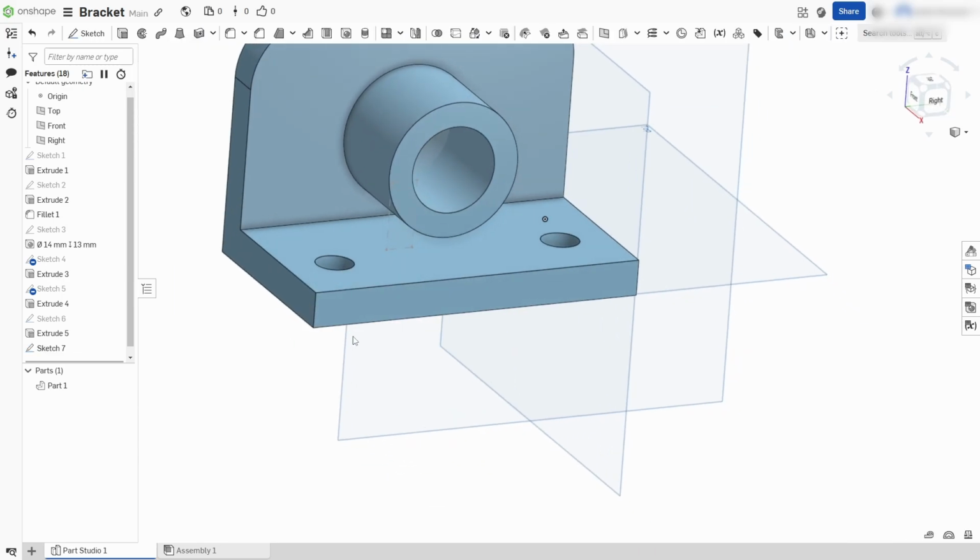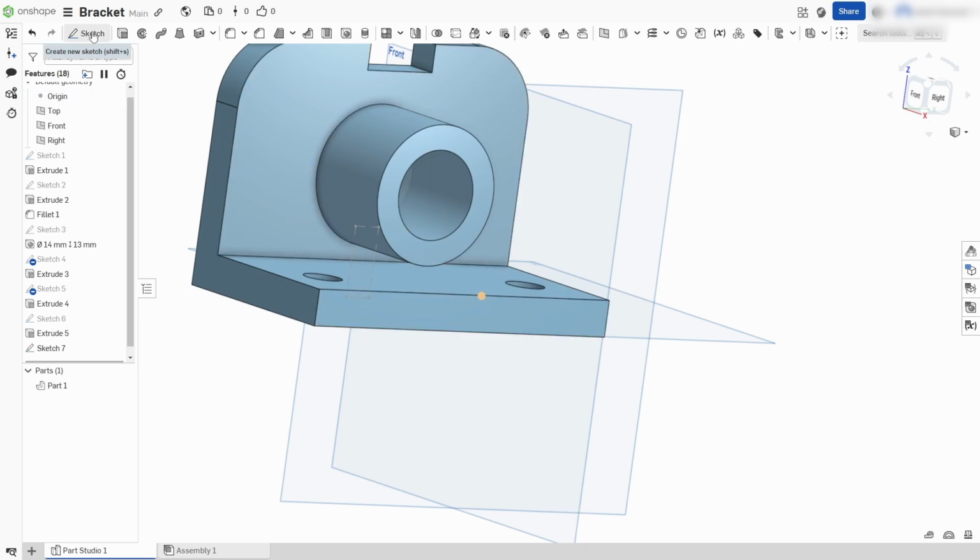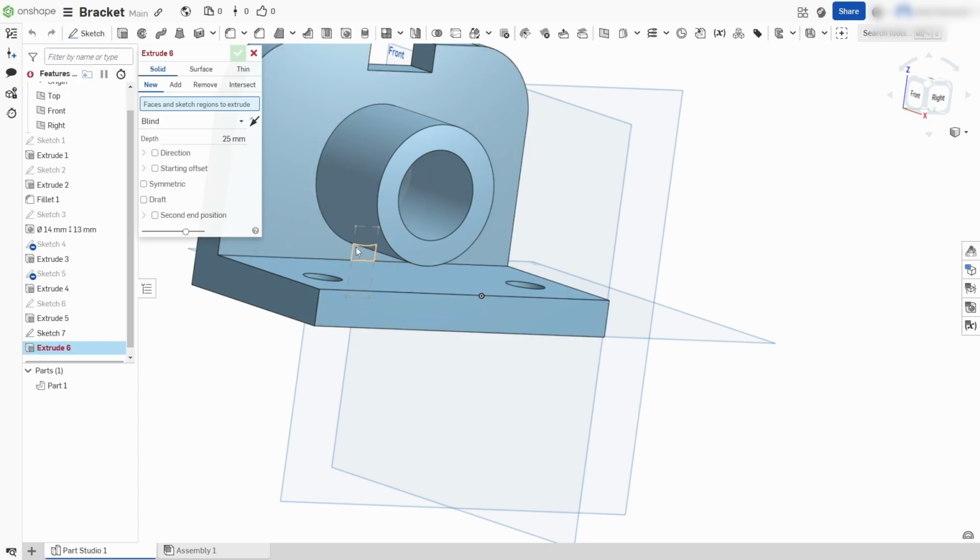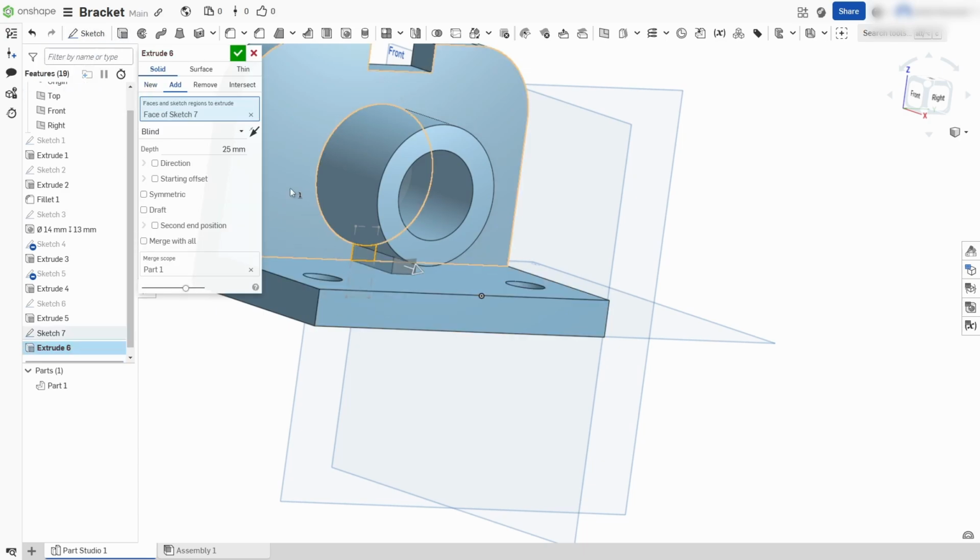So now we're going to pull this out. So we're going to extrude that. Yeah, we can just extrude that one little chunk there. And this extrusion is going to sit up at the top of this face. So we got 38. And we want it to go a little bit higher. So maybe take it all the way. All the way is 76 minus 13. There we go. To the total face.